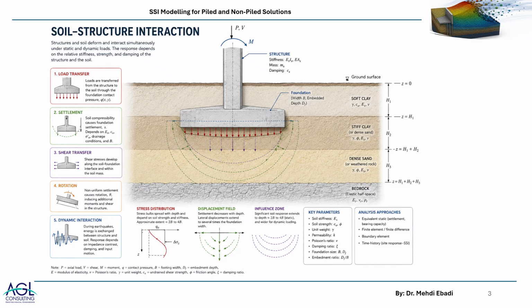This is under the loads that are applied by the structure to the soil, and there is a stress redistribution in the soil, which on the other side influences the structure, both from the aspect of sufficiency of the strength of the soil to resist against the forces by the structure, or the displacements that occur in the soil, which cause deformations in the structure, and that deformation in general will result in forces and moments in the structure, which has to be safely within the capacity of the structure.